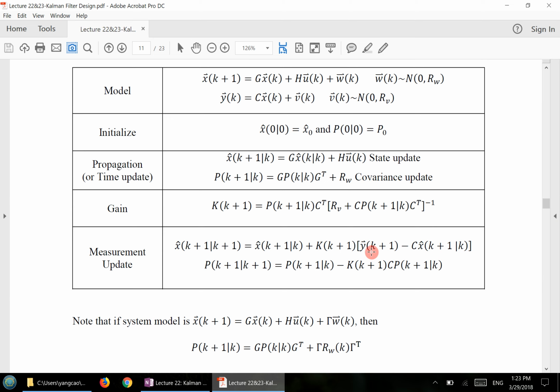System output, in other words, what output? Where do you get the system output? How do I get it, from what type of device? Sensor. So this is from the sensor here, and then you use the Kalman filter gain multiplied by the difference here. Okay, does that make sense?